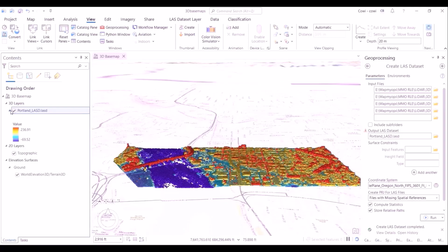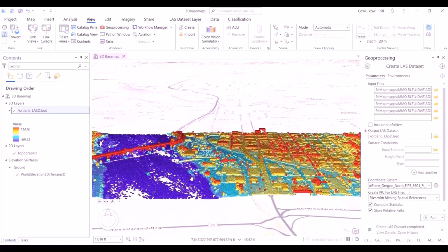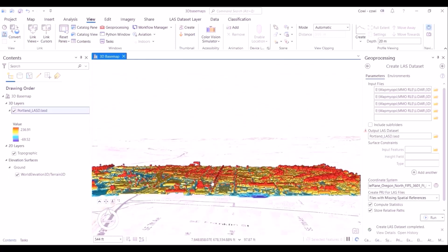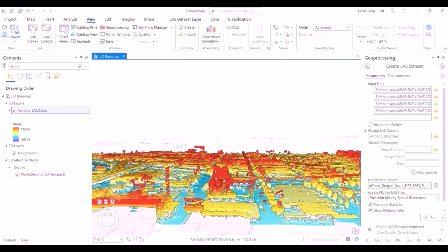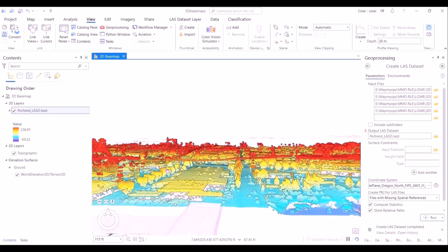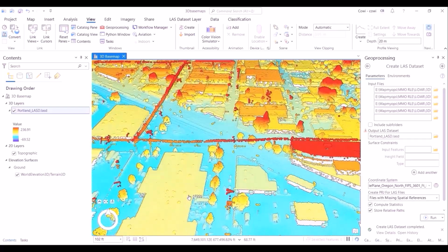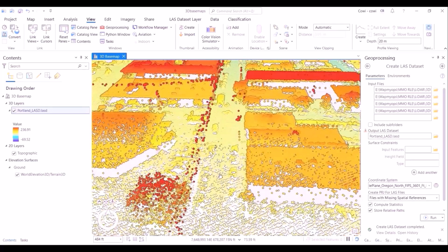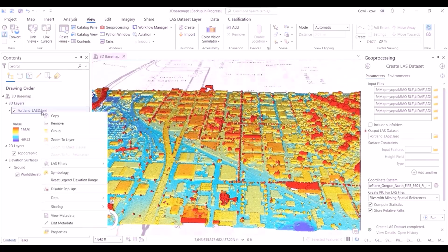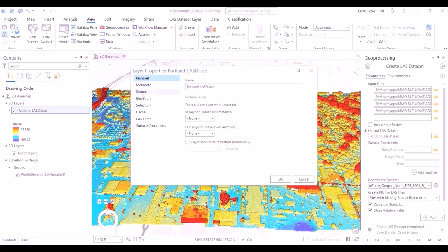It's a vivid mix of various colors. You can see that the high elevation values are in yellow and red and orange respectively, whereas the low elevation values are in blue, dark blue respectively. The measurement is in feet and not in meters. This is something which you must be aware of. So 236 feet is the tallest spot and minus 70 feet is the bottom spot in the particular LiDAR dataset. This data has been acquired using airborne LiDAR, as in via an aircraft or via a drone.